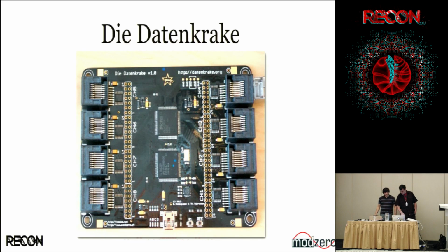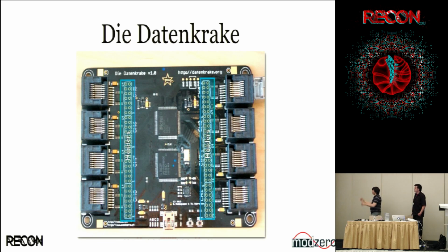Okay? So, yeah, and the last one's the most important part, at least for me. I want to have access to all of the signals. And on these headers, on the side where we have the ARM and the FPGA, you have the unterminated signals. So basically whatever the FPGA is spitting out. And on the right and left, the outside world facing the RJ45s, you have terminated signals. But again, as we said before, you can disable the buffers and do something custom.